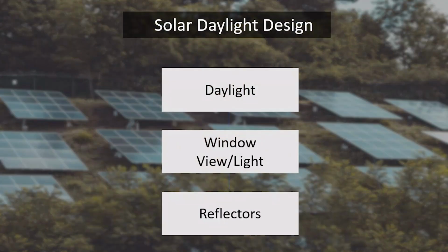When we are talking about solar cooling, shading devices are also required, such as trees or some other shading, insulation and evaporative cooling. But one thing must be kept in mind: the goal in a solar building is the optimum balance of mass, glass and insulation for a particular site and house design. The third thing of solar building design is daylight.